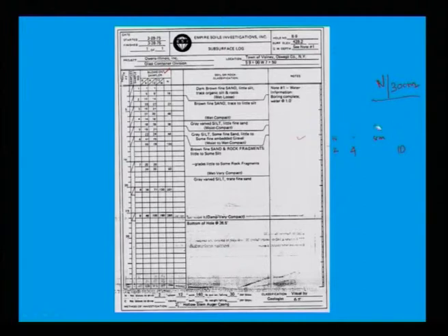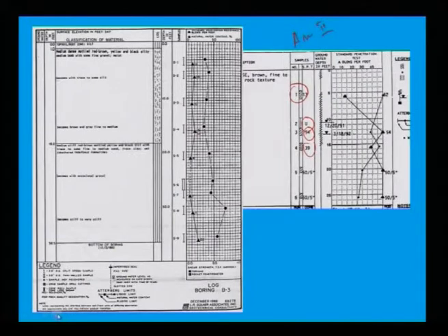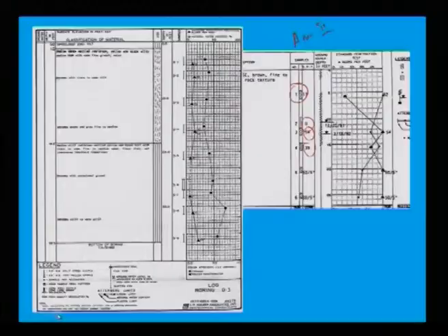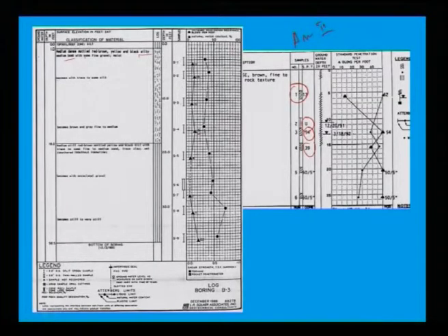Now, this is about your field test report. Whatever I have shown you is about your field test report, SPT N and moisture content, where you collect your sample, at what depth you collect sample, and whether it is a disturbed sample or undisturbed sample you collect, where is your water table, and general soil classification. This is annexure 1, general soil classification, you say silty sand. Whether the general soil classification is correct or not, that is again a question mark.